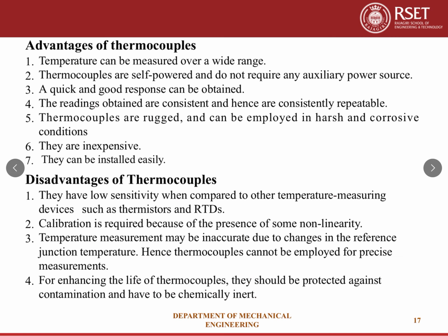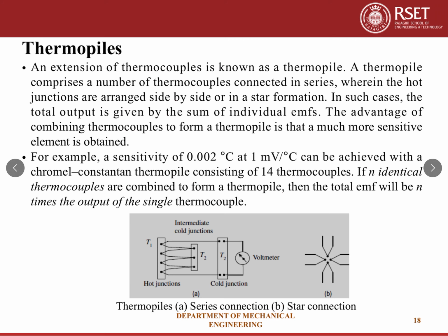There are certain advantages and disadvantages of thermocouples. Temperature can be measured over a wide range. Quick and good response can be obtained. The disadvantages: they have a low sensitivity when compared to other temperature measuring devices like RTDs or thermistors. Calibration is required because of the presence of some non-linearity. Okay, these are some advantages and disadvantages of thermocouples.